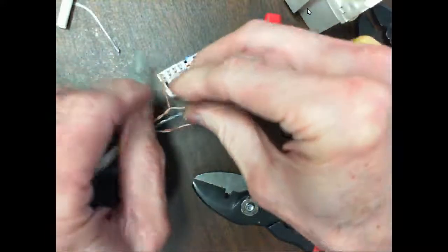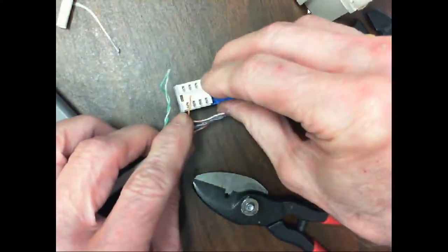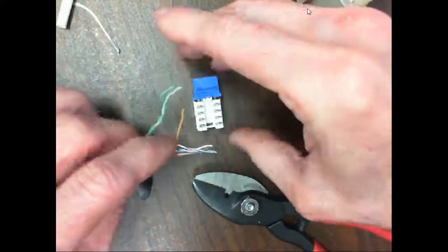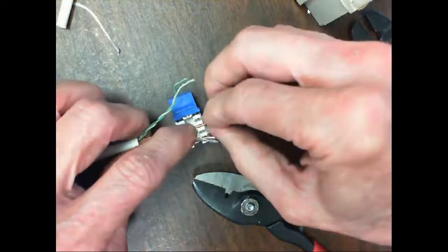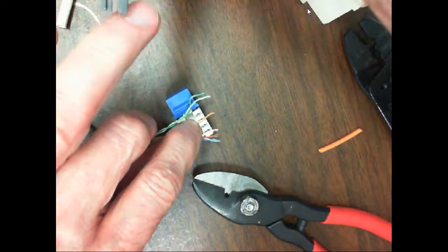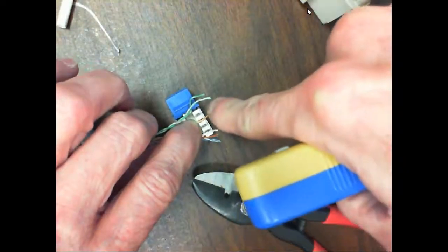We'd come up here and we'd lay it in the groove. Can y'all see me? I'm sorry. So we come in the center, so our wires are going to come out this side right here. We lay it in the groove, then we take this guy and we want to point this blade toward the end that we want to cut off, right? Then we'll come in here and we'll set it down on there,